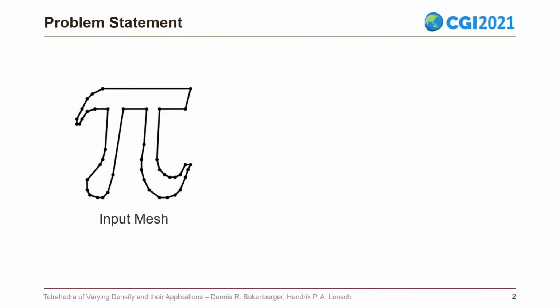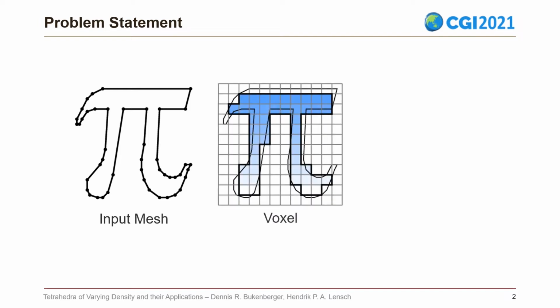Mesh geometry is usually given as a set of vertices connected with triangular faces. However, to simulate varying density for such objects, a common fallback solution is to use grid or octree-based voxelizations of the volume, as these small boxed volume entities are easily integratable. This, however, is only an approximation of the real volume, as the discretization introduces heavy aliasing bias.